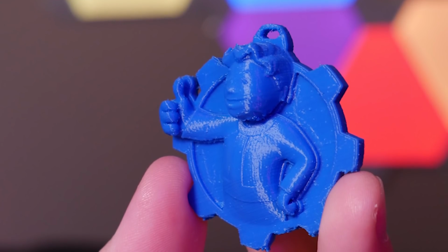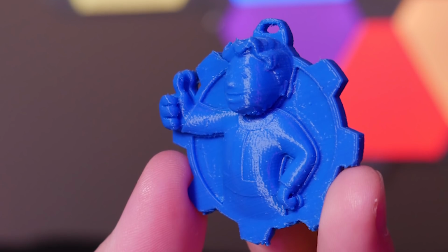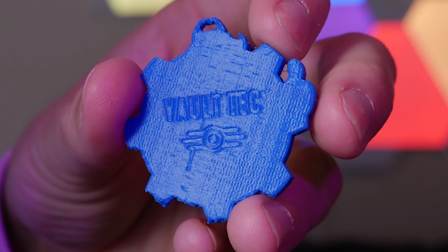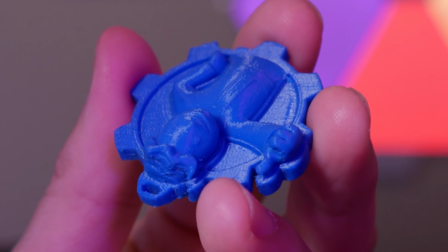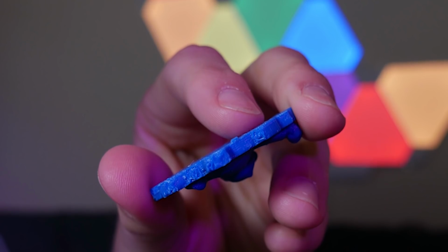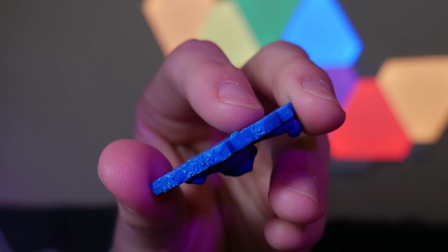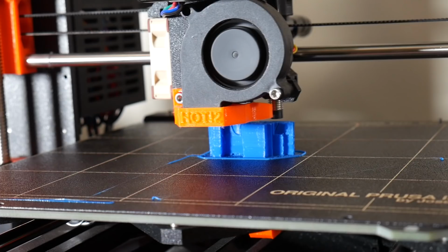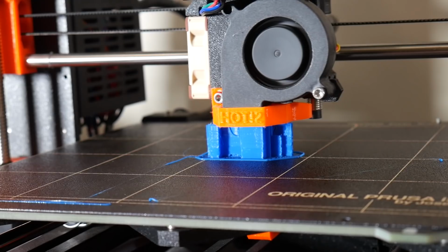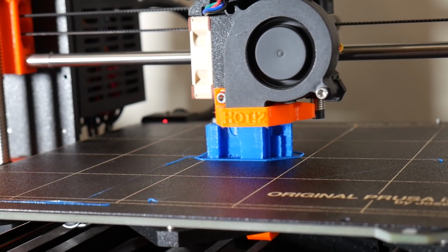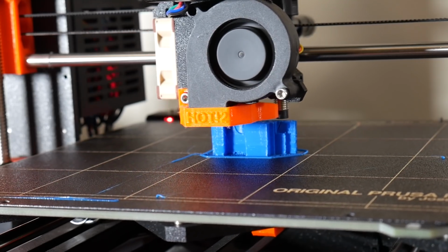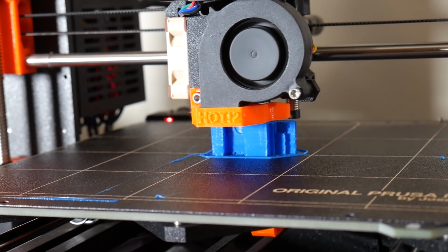Printing this with a 0.4mm nozzle really does start to show the limitations of this technology, and although the front and the back looks pretty good, it's a little bit rough and the bottom looks very rough. But having that raft really did make a difference to keeping the support structures stuck down, and I think if you're in a pinch and you only had this technology to print something this small, you definitely could do it with that 0.1mm layer height setting and the small tweaks that we did.